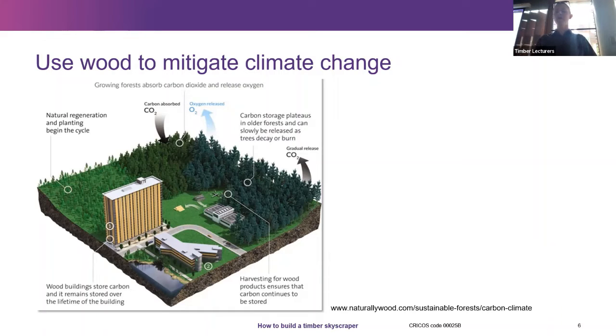Right, so that's the way how we can store some carbon. And because it's a material that just grows, so nature does it for us, there's also very little energy involved in actually extracting it. If we extract iron ore to make steel, or we build a quarry like we have at Mount Kuta to get the aggregate for concrete, that takes a lot of energy. Then it takes energy to process it. So making steel is very energy intensive, because you'd all know from your material classes that it has a high melting point, and to really get the temperature that you want takes a lot of energy.